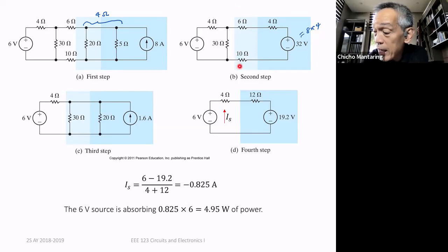When you have elements in series like this, you can change the order of the elements in the branch, and that's not going to affect the rest of the circuit. Because when you apply KVL inside here, it doesn't matter what the order of the elements are, you're going to get the same KVL equation. So I just get the sum, and that is equal to 20 ohms. Right? So now I can convert this whole thing into a current source.